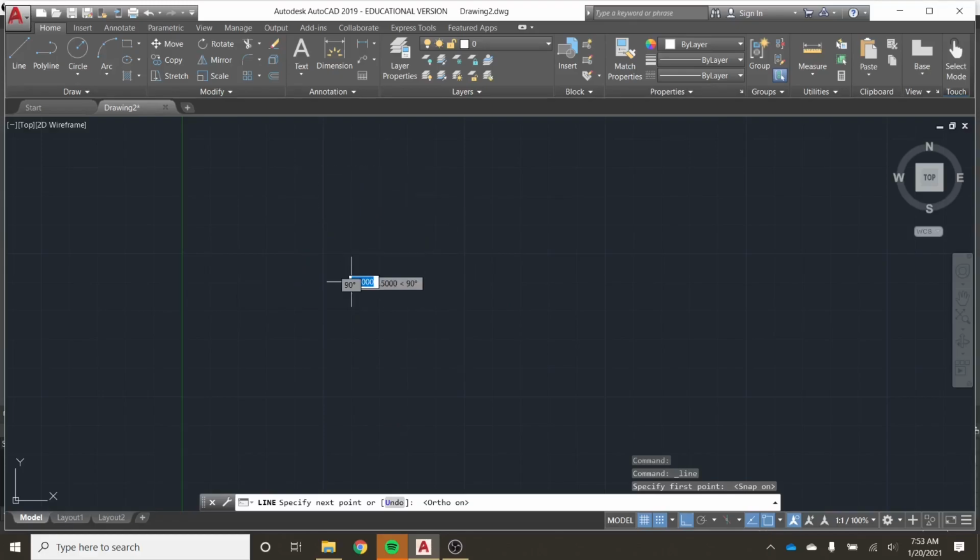So I have to go from my starting point on a coordinate. You can think of your starting point as 0, 0 on a coordinate quadrant layout, and you have to go left or right, up or down. So that's ortho, and I'm going to go ahead and click the line to finish. Now if you notice, it wants to continue drawing a line. It assumes that you didn't want to draw just one line, that you wanted to do multiple lines.